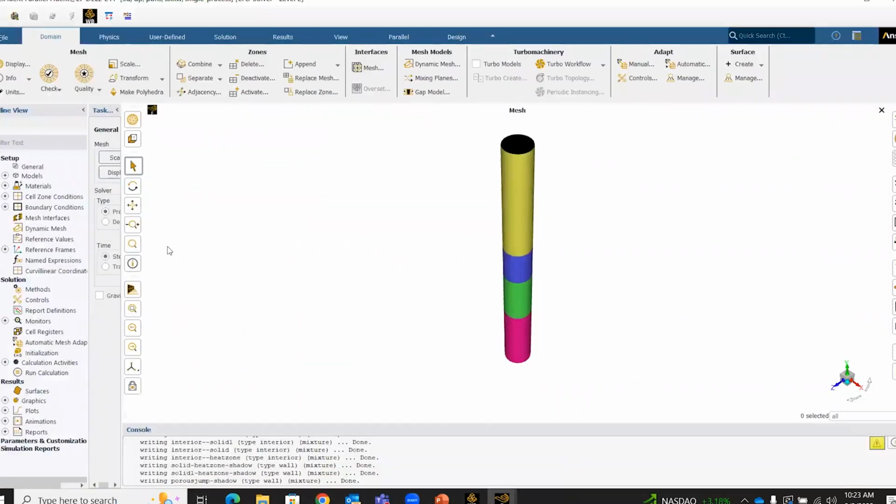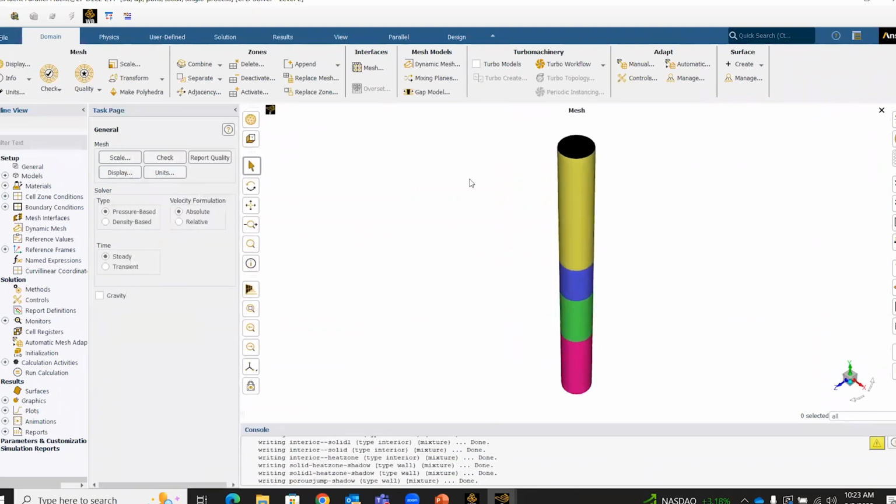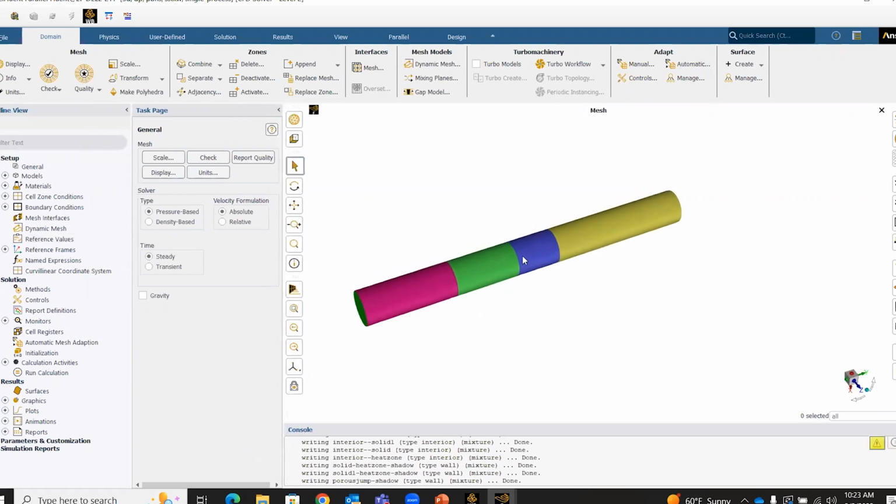So you should be seeing my Fluent window on your screens now. Okay. This is a simple example pipe. I didn't check the dimensions, I just built something arbitrarily. And I've loaded this in Workbench. I've already opened the file to save us some time. The mesh is quite coarse again, because I don't want to spend too much time with the computations. But basically, one of these zones is going to act as a heat source. There is an inlet on one end and an outlet on one end.